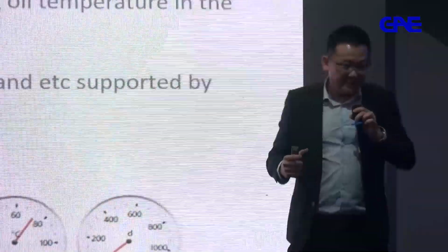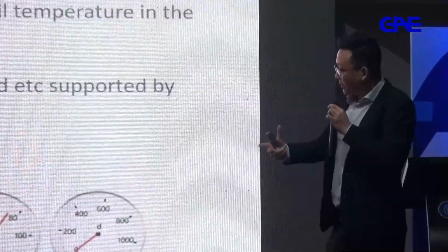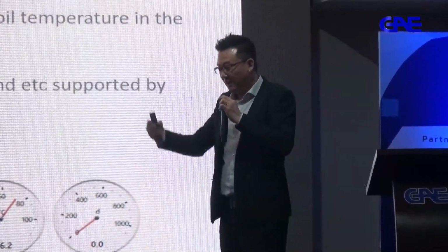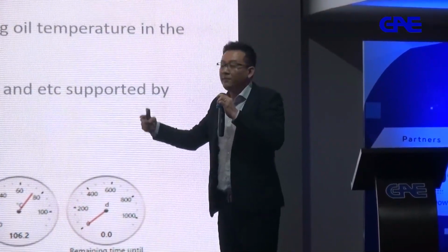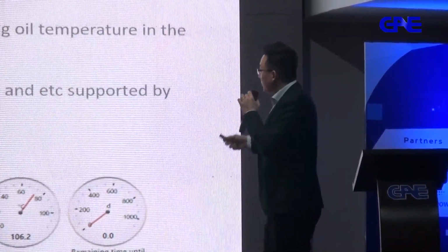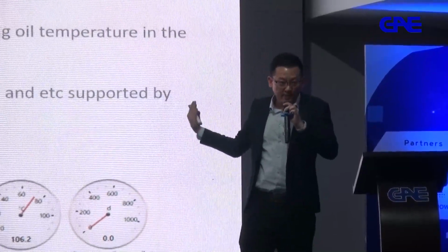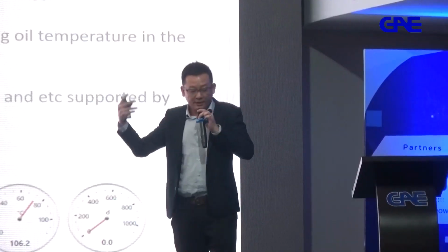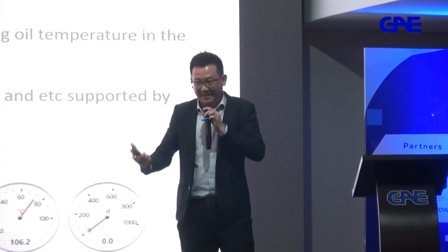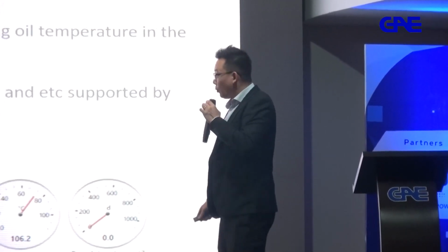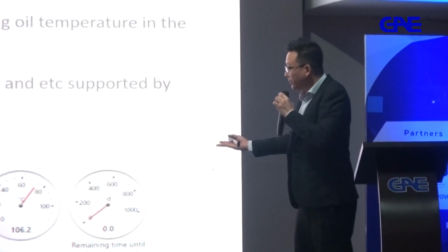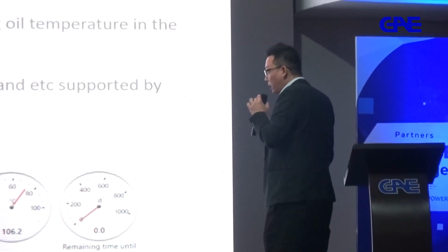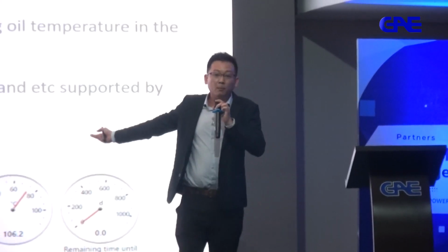You directly measure the relative saturation, in percentage RH, relative humidity. From there we convert to ppm, parts per million, using the oil temperature in the monitor, because inside the monitor itself we have a temperature sensor as well. Additional modeling, such as moisture in winding paper, bubbling temperature, etc., are all supported by the thermal model.